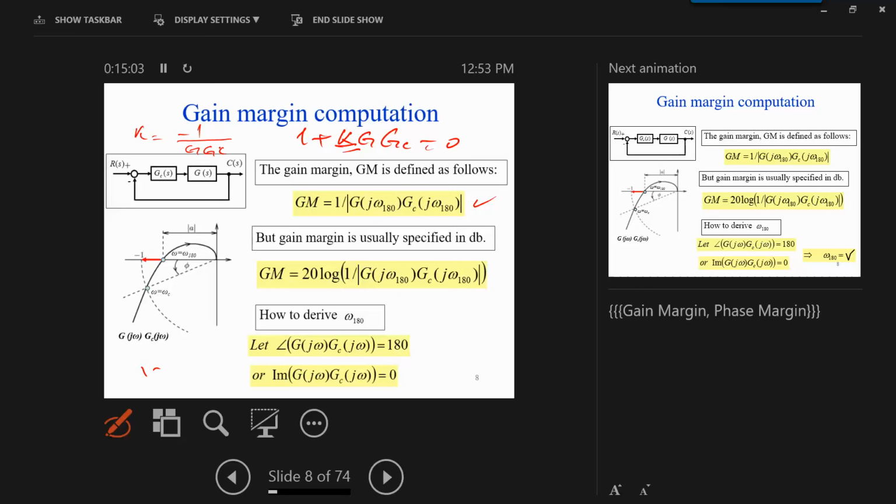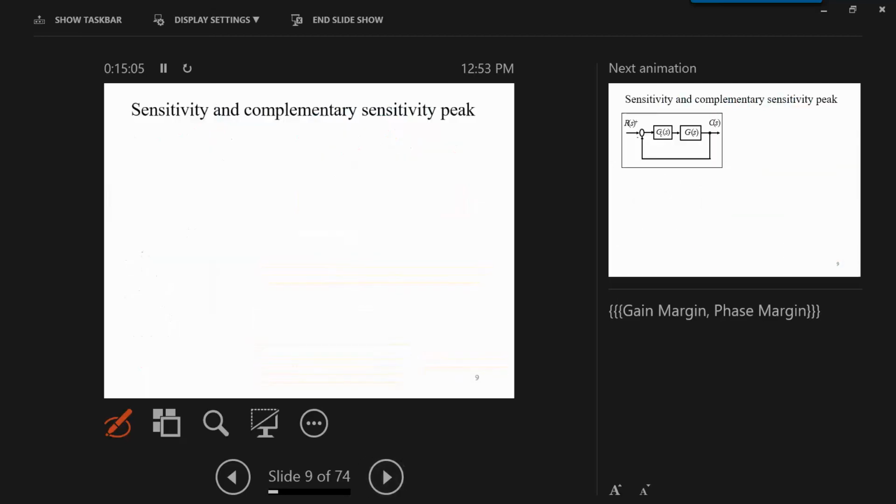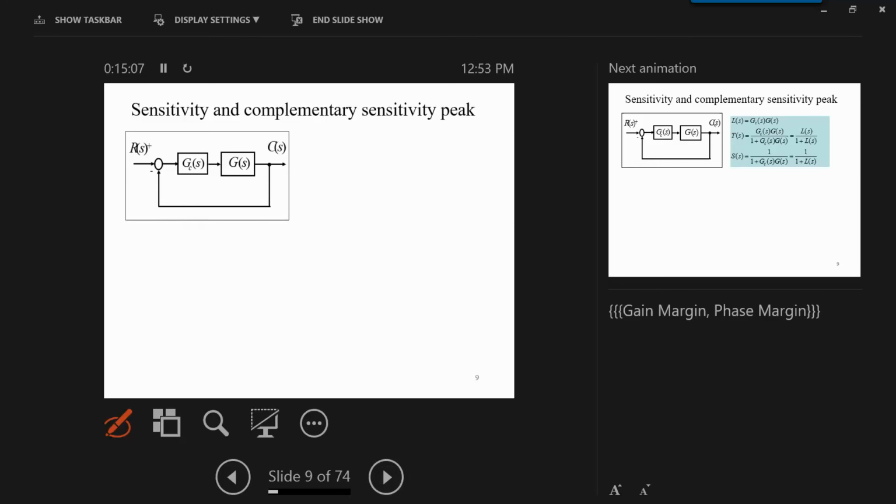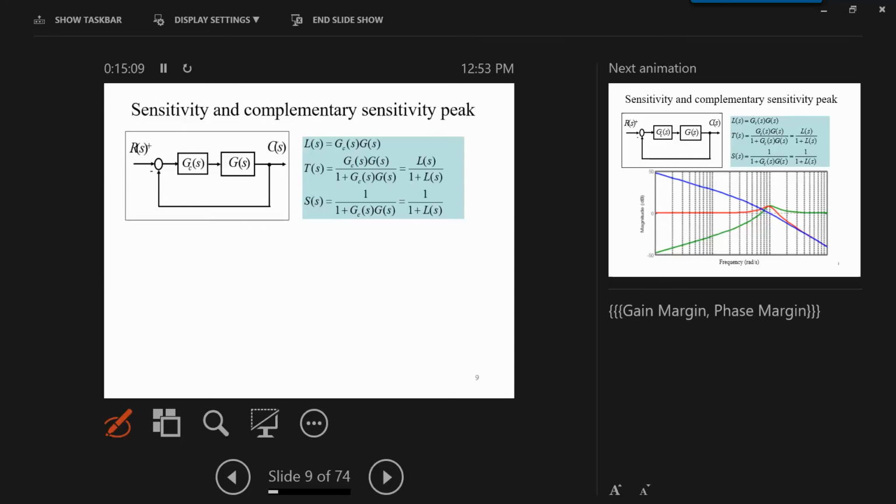We get the gain margin from the product in dB. Do we leave it in dB or do we have to change it? The gain margin, you can write it in dB. You have to use the units. If you are asked what is the value of the gain, you have to convert it from dB to the actual value of the gain. And this is simple, right? Yeah.